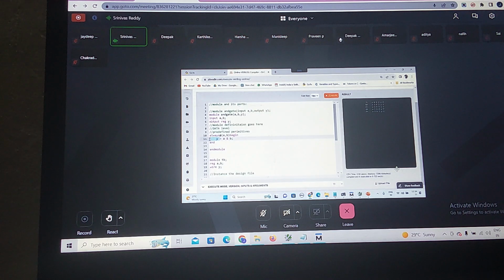So we'll see why this happens. Those questions will be addressed when we talk about the behavioral model. Correct? In the behavioral model, these outputs are declared as reg data type. If I run this program without the reg data type, it says that Y is not a valid left-hand side value in the TB output. So Y is declared as what here? In this case, it is declared as a wire data type. In this program you can see Y is declared as what here?